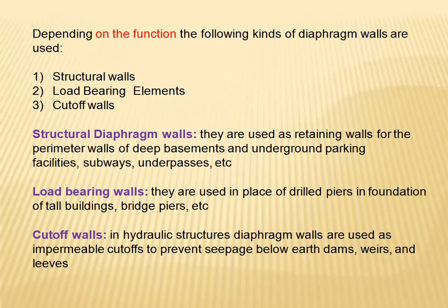Now, diaphragm walls are also classified depending on function. The functions are structural walls, load bearing elements and cut-off walls. Structural diaphragm walls are used as retaining walls for the perimeter of deep basements, underground parking, facilities, subways and underpasses.